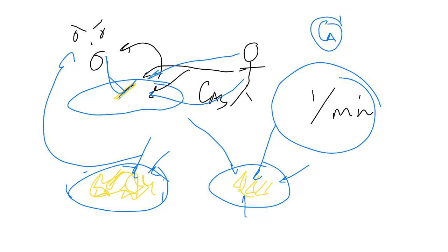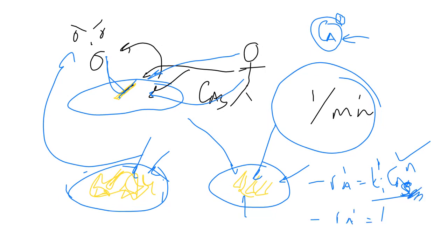Because the external diffusion is always a first order process. So you measure first order, yes, in certain instances when the true reaction rate is actually first order, intrinsic. However, you can actually mask this rate when you think you have the surface concentration there, when you don't realize that you are actually measuring this rate, kCAm times Ca bulk. You are actually measuring that rate. So that is the first reason that you need to take cognizance of that.